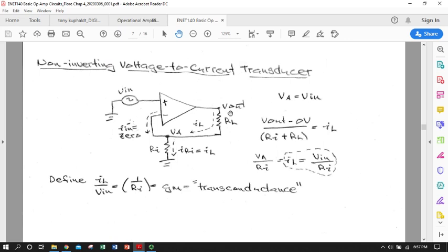And of course, as I went through with my long-winded intro there, you could express the output voltage, which would be the drop over that load resistor, and the input resistor reference to ground. If you were using that as a test point in the circuit, for instance, it would give you an indication of current. Or, of course, you could measure the current directly by putting an ammeter or current sensor in series with the load. So, transducer, voltage to current, amplified current, output current ratioed to input voltage is transconductance, G little m.